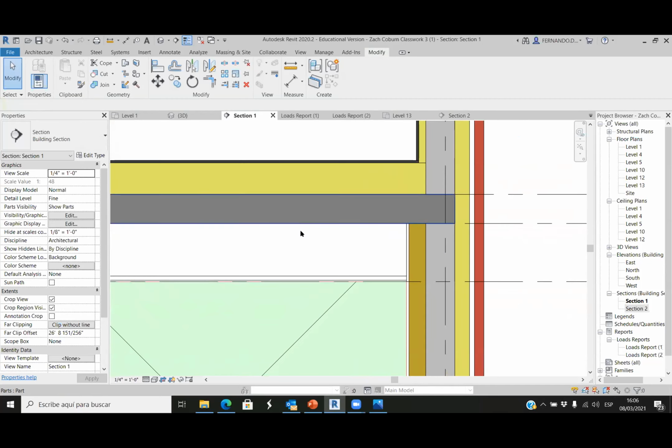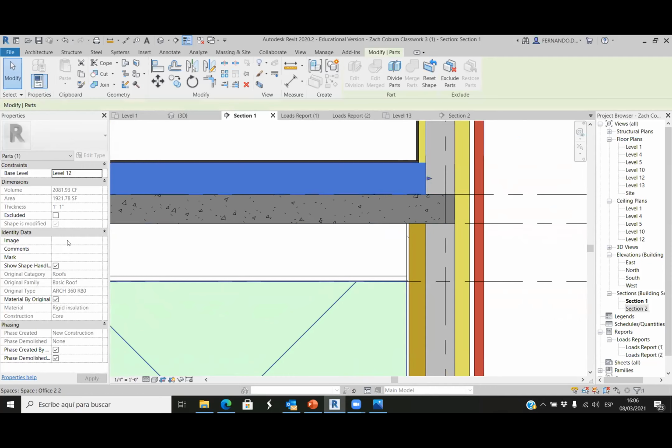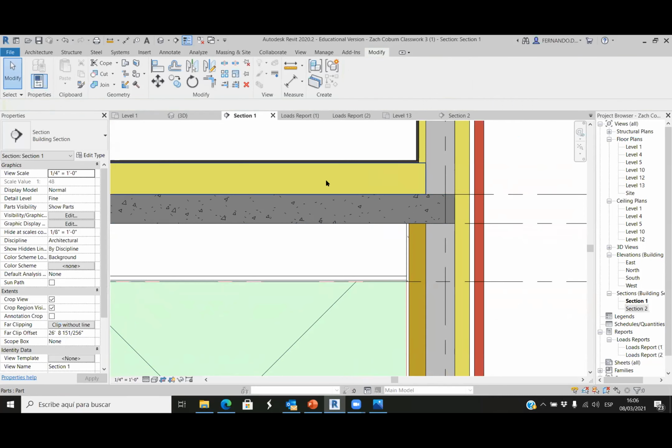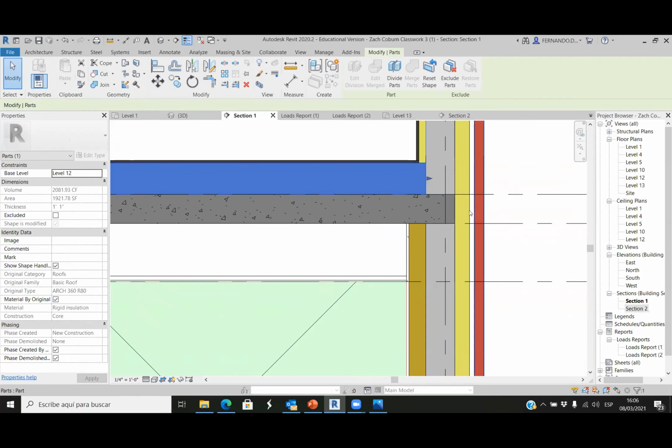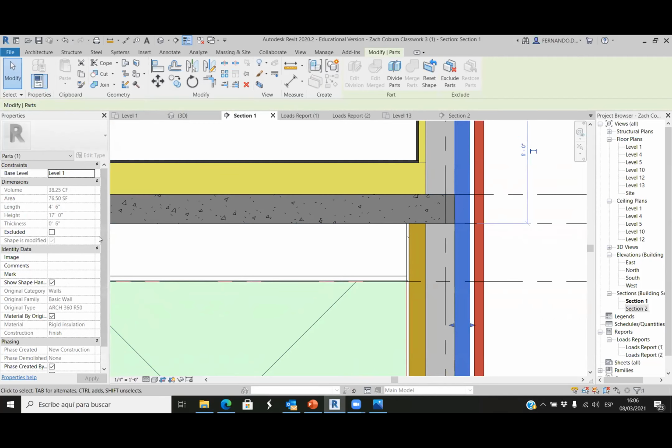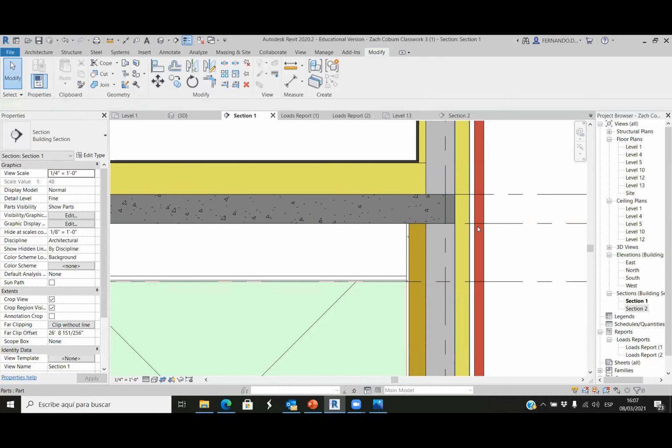If I try to go this way, the roof, we have a foot and 1 inch, so it's 13 inches as well of thermal insulation. But here, yeah, we have all this width of concrete, but we only have 6 inches of thermal insulation here. Okay, so this is the weakest point. We can quantify that. So how much heat are we losing through this thermal breach?